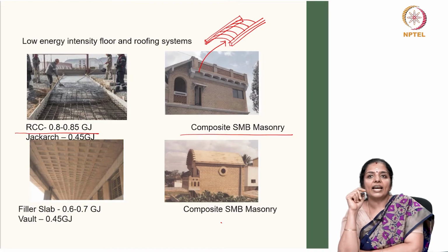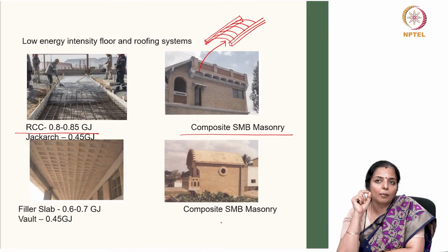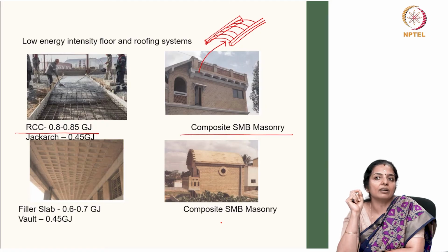So, this jack arch is classically defined as a structural element in masonry construction which provides support at openings in the masonry. Its other names are flat arch or straight arch. Unlike regular arches, jack arches are not semicircular in form. Instead, they are flat in profile and are used under the same circumstances as lintels.